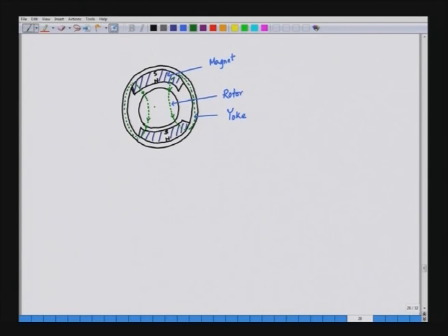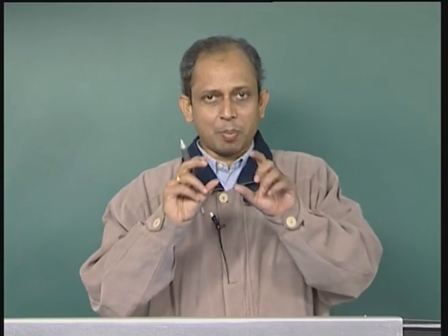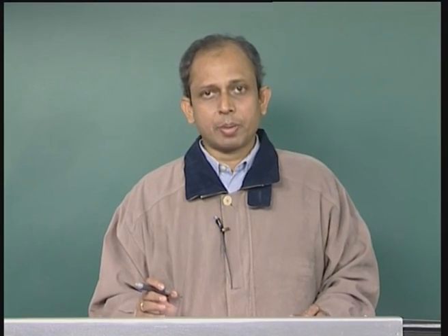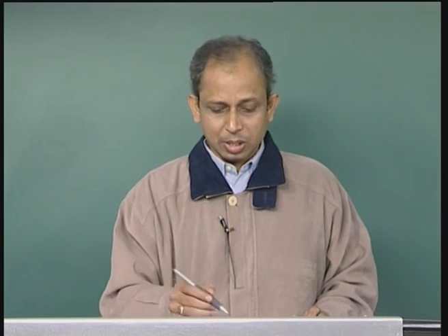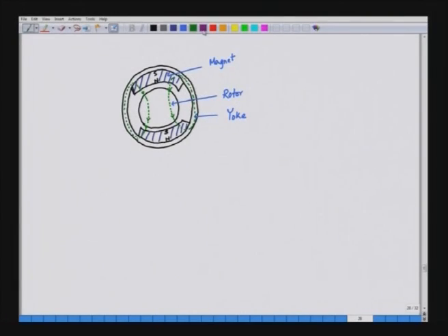So, this is basically a typical field structure using ferrite magnets, and in ferrite magnets the magnets are basically short, but the width is large here. This is the width of the magnet. So, the cross sectional area is large here, but this length Li is small here, and this is to maximize the BH product we are having this magnet.